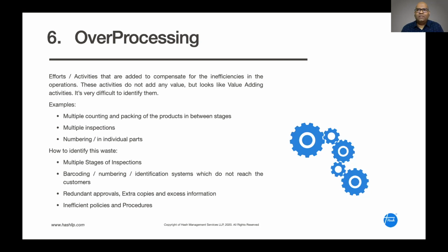Okay, are we adding any value during inspection? Inspection is a process where we are only segregating the good pieces and bad pieces. We want to make sure that the bad pieces don't go to the customer. That's all. Is there any change that happening in the product during inspection? No. The defect originates in the process, and after the process is done, I am sitting separately and segregating good pieces and bad pieces. So is there any value addition? There is no value addition, right?